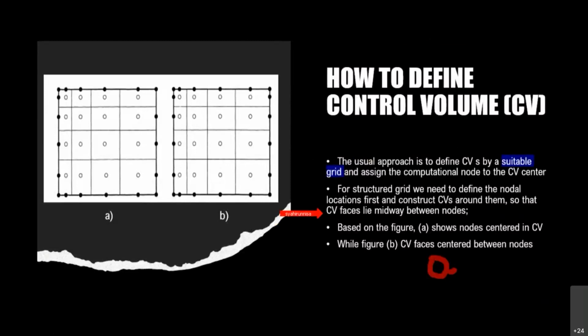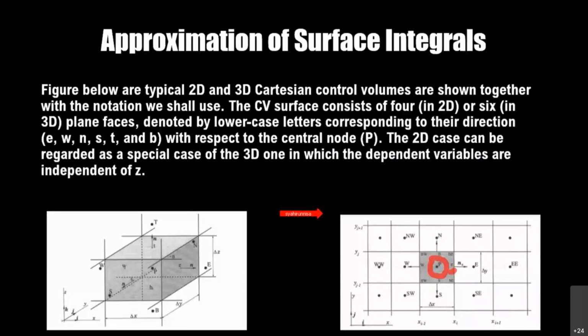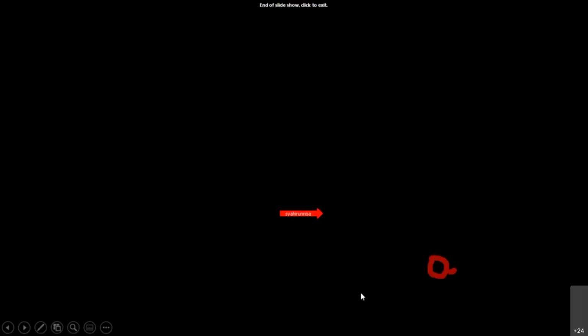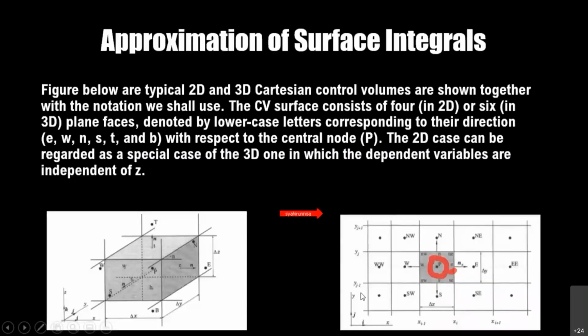Najiha: Yes, hello, please proceed. Okay, how to evaluate flux at control volume corners? Thank you, Najiha. To evaluate the flux at the CV corners, it actually needs a higher order approximation of the surface integral. That means a fourth order approximation, the Simpson's rule, which estimates the integral over SE as